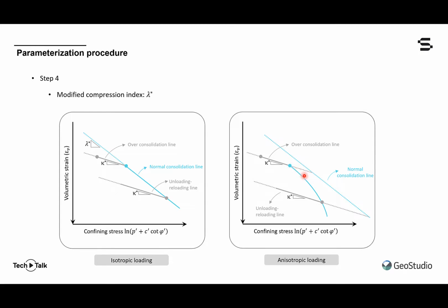So for example, if we continued with triaxial shear up to this point right here, there would be a magnitude of total volumetric strain comprising both elastic and plastic. That would be the vertical distance between this point and this point. But if we unload back to the confining stress that is just under here, then this short portion right here, short length, would be the recoverable elastic strains, and the remaining portion would be the irrecoverable plastic strains.